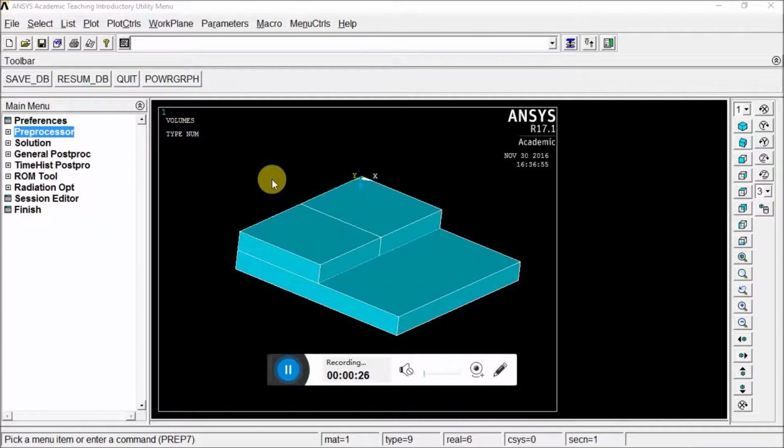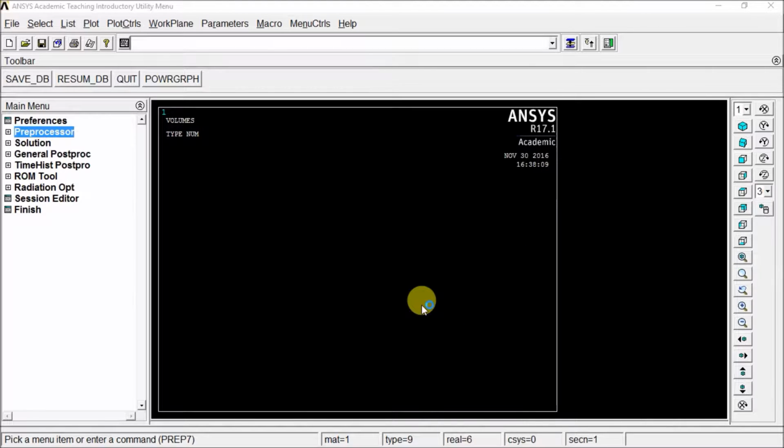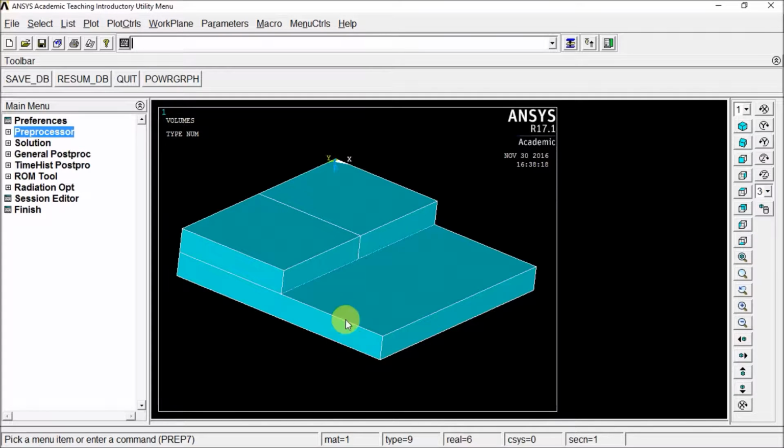If we use the left mouse and click and drag, nothing really happens. Same thing with the scroll button. But if you right click and drag, you're going to make this little box, and that's going to zoom into that box that you draw. So if you accidentally right click and drag somewhere, say over here, you're going to zoom into black space. Sometimes that'll happen. What you want to do if that happens is hit this little fit view right here, this magnifying glass, and that'll bring it back into shape.